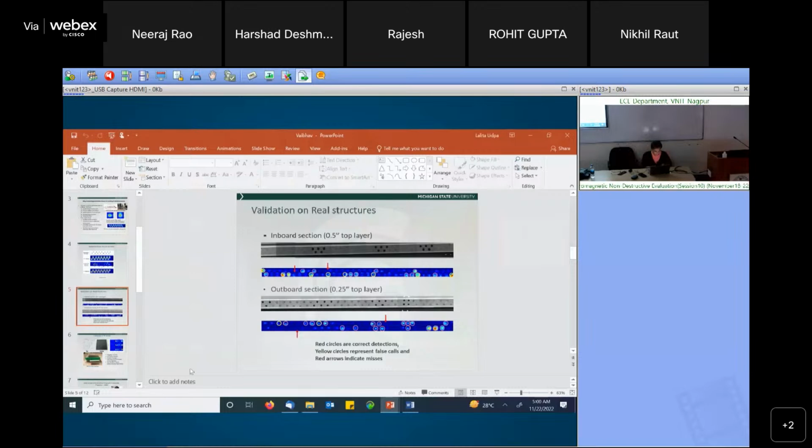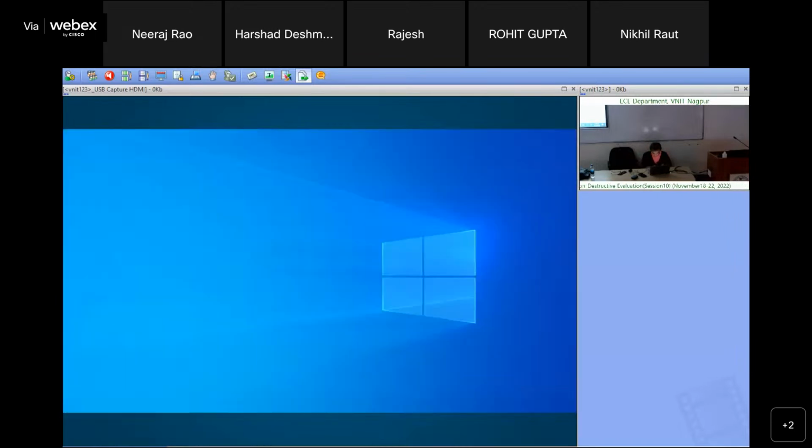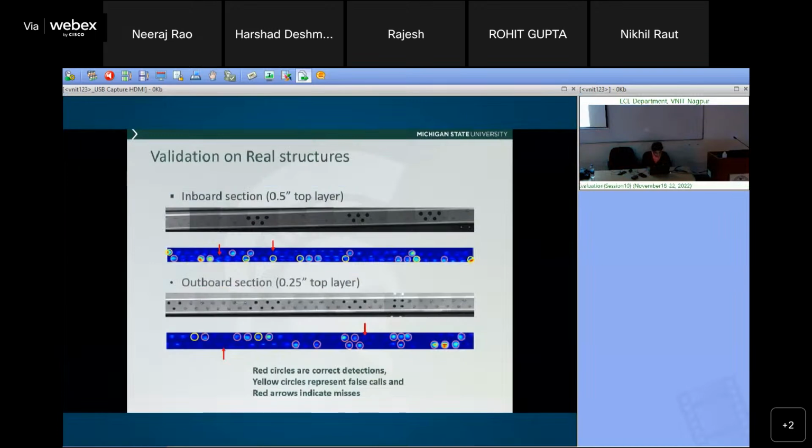The X-ray basically gives us a ground truth. Wherever you have a dark circle, those are steel rivets, and these are aluminum rivets in between. When you take an X-ray image, it will not tell you the difference between the aluminum rivet and the host metal, whereas when you have steel, you have these dark circles.